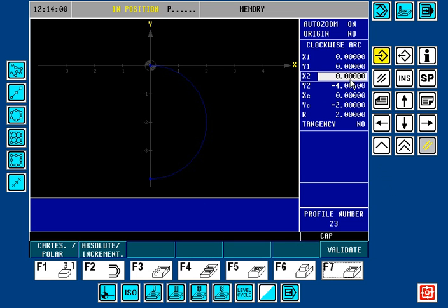So one of these values will have to be adjusted or eliminated so that the profile editor can solve it and put the adjusted value in. If I were to adjust this point to minus 4.004, enter, it turns purple, which means it's now solvable. So simply moving the endpoint in a more favorable direction by 1 thousandths allowed us a solution here.